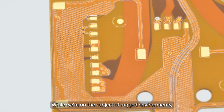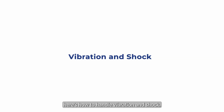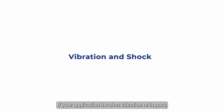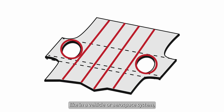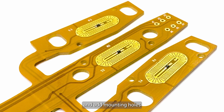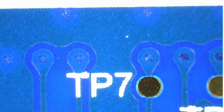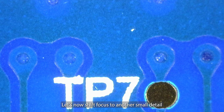While we're on the subject of rugged environments, here's how to handle vibration and shock. If your application involves vibration or impact, like in a vehicle or aerospace system, you need to anchor your flex. Use fasteners, clips, screws, or relief bars to lock things down, and add mounting holes to stabilize the layout and prevent tearing under movement.